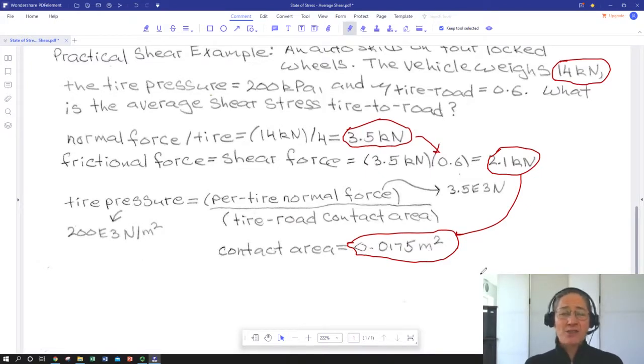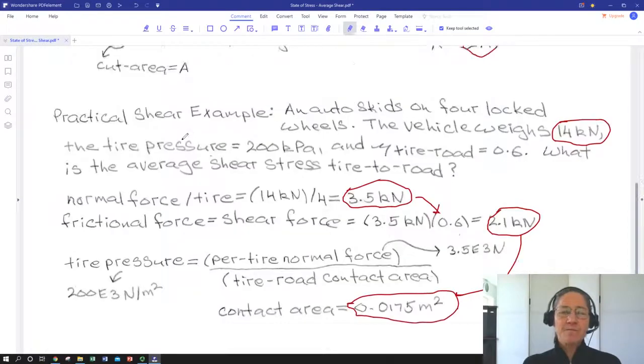We might want to make sure that the lamination of whatever kinds of reinforcers to rubber can withstand at least that much shear stress without delaminating and failing. That might be one reason we would need to know it. That would be a lower limit of shear stress, the shear strength of that sort of composite tire material.